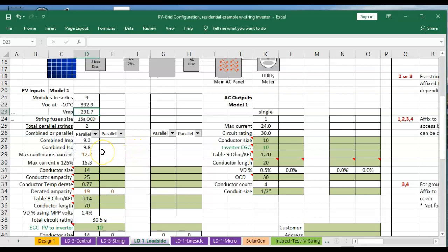And we have 4 conductors. We have 2 parallel strings running down. And so we're sizing our conductors for each of the circuits. So we have our max current provided for us here, max current provided for us here, and then the ampacity requirement of the conductor and overcurrent device if we needed one. And then we have to find a conductor that's rated for 15.3 amps. So you hover right here and it says, hey, you need to look at table 310.15(B)(16).